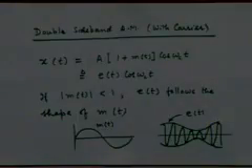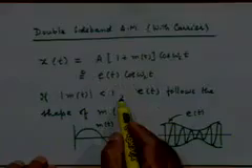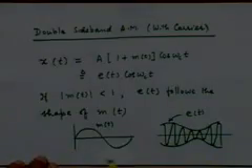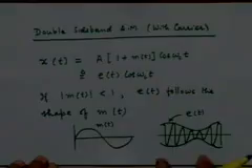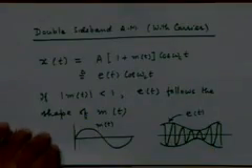If it crosses the time axis, we will have a problem, because then we will lose the proportionality of the envelope that we are looking for with respect to m(t). So that's why this condition is required, that mod of m(t) should be less than 1, right? So that's the typical time domain waveform of amplitude modulation with carrier, okay, as against the waveform that we saw yesterday for amplitude modulation with suppressed carrier, without carrier.